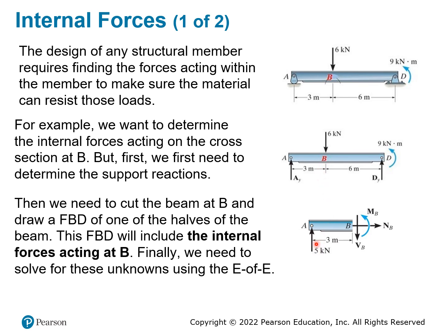And you can assume that when you cut the section at point B, you are going to have some reaction forces. When you cut something out, you put in the reaction forces, and these reaction forces are of three different kinds. The first one is the N of B. This is what we call the normal force. The normal force is the force perpendicular to the cutting face where you cut at point B. So the normal to that cross section is going to be the normal force of B.